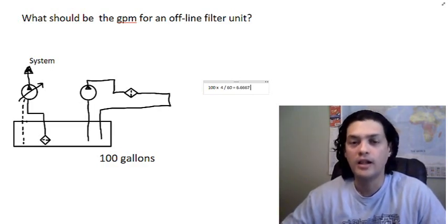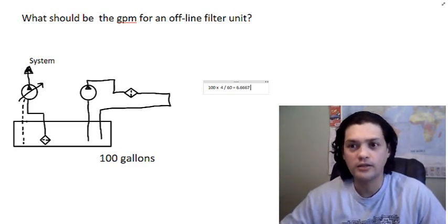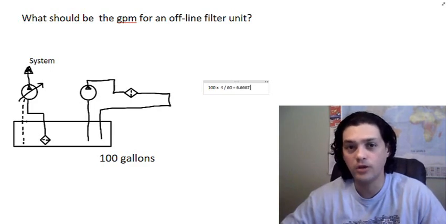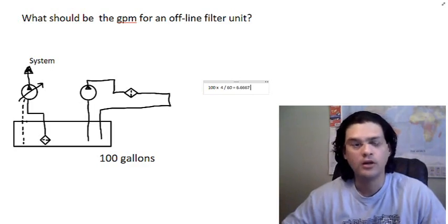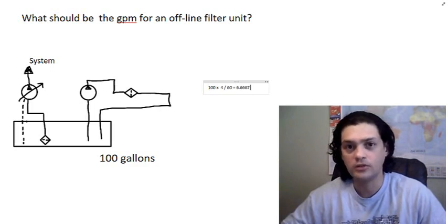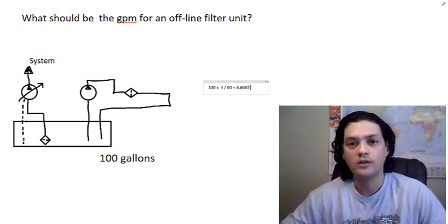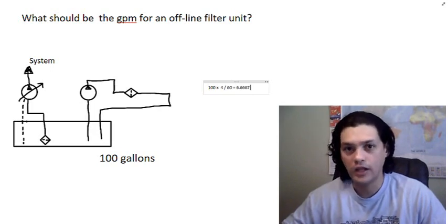Some components need cleaner oil than others, so what you do is take the most sensitive component and match the contamination level of that sensitive component, and that's the contamination level you should keep in your reservoir. So what goal would that be? That's according to ISO 4406, and each hydraulic component manufacturer recommends a certain contamination level for different components. Most of them are all standard.